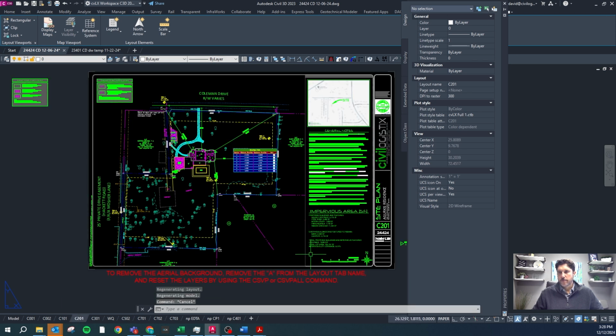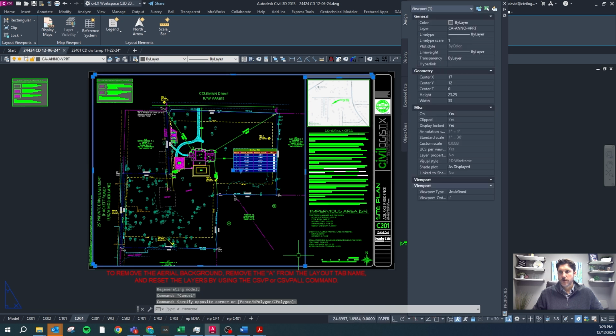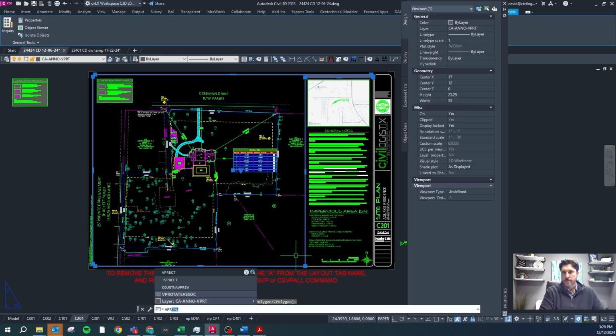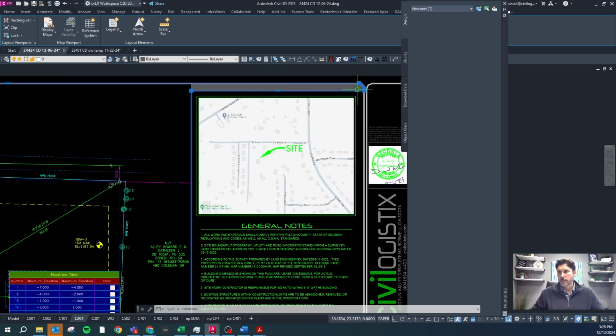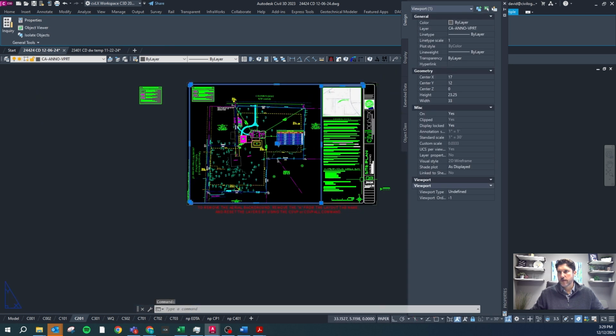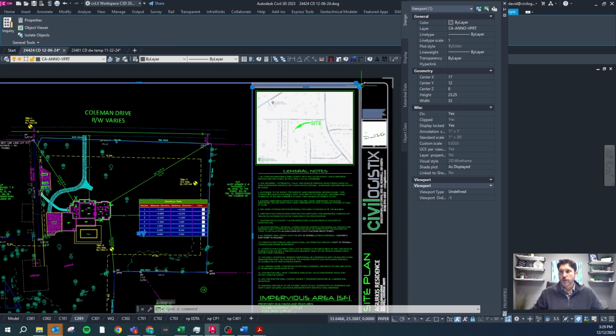When you're setting up, another command you'll want when you're setting up new projects is to select the viewport and type VP rect for rectangle, and it's going to make a rectangle at the farthest extents of the boundary, which goes all the way out to here, because you can see this goes out all the way to the edge. Don't change this.